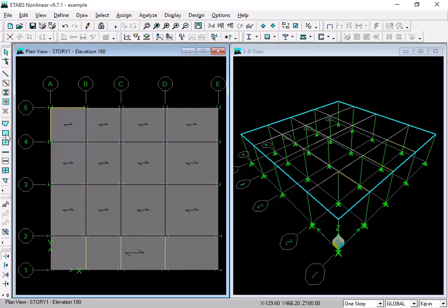You may have a storeroom here, with a different live load. For example, if this long place is a corridor, you can have it as one panel and apply the loading of a corridor. So based on the architectural plan, you can decide which bays you can combine while modeling the slab and which you have to keep separate.